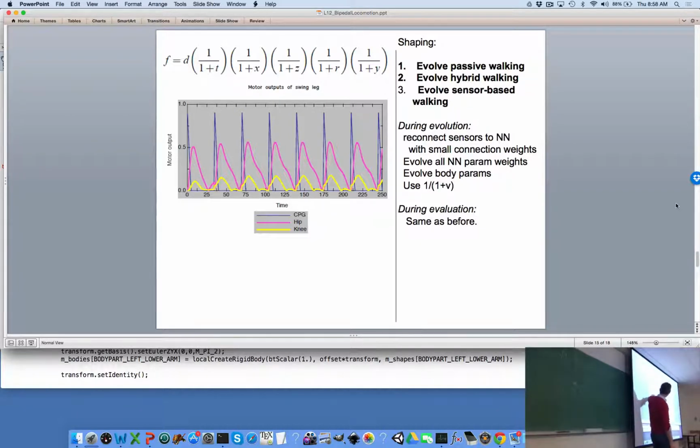So if you look at the knee, that's following as well. The knee is rotating backwards, right? So it can't hyperextend its knee. In this case, a non-zero velocity for the knee is telling it to rotate the knee backwards a little bit. Why does the robot rotate its knee backward at this point in the step? Keep the lower half of the leg perpendicular to the ground. To keep it perpendicular to the ground.